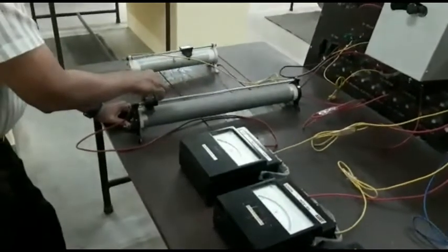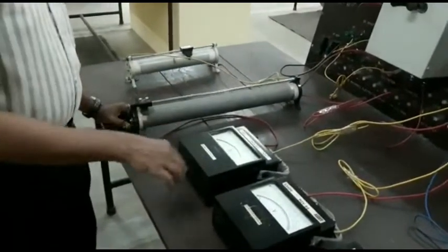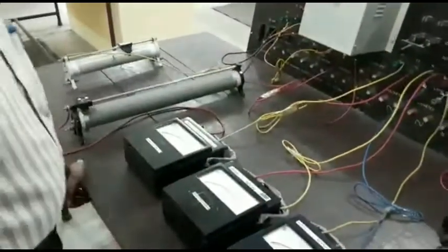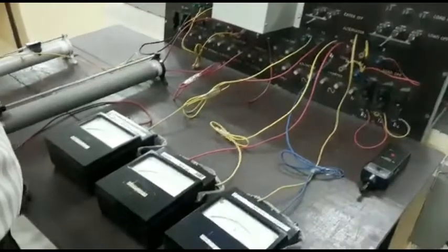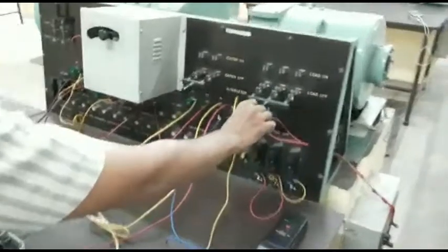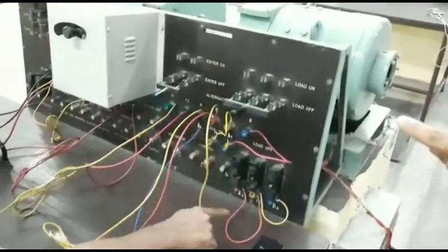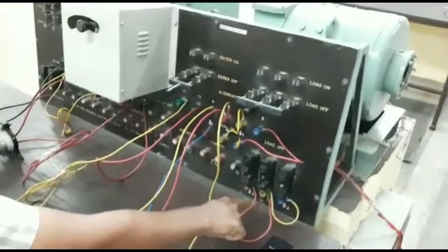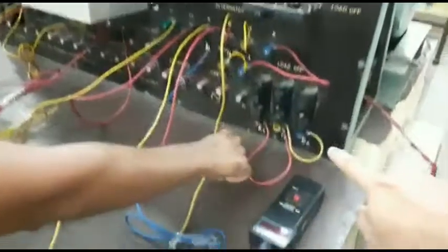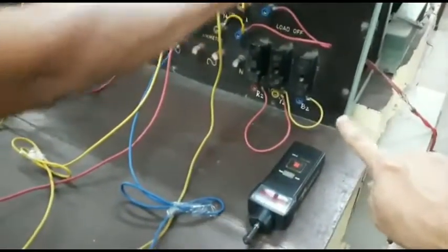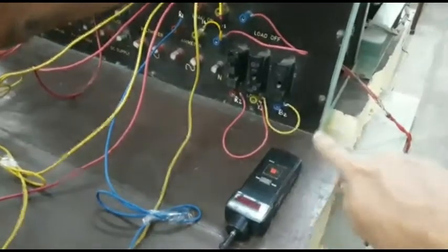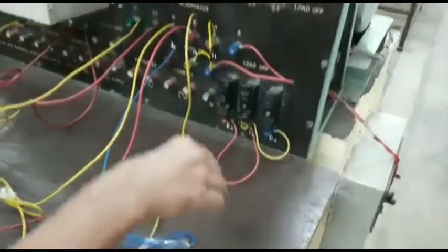That is what sir is doing now. Yes, now the OC test is over. Now the second thing you have to do is the short circuit test. For this, you have to switch this load from the off position to the on position. There is also a knife switch for that. When you switch on this knife switch, all these terminals R2, Y2 and V2 that you see in the bottom portion get short circuited, where the three terminals are shorted.